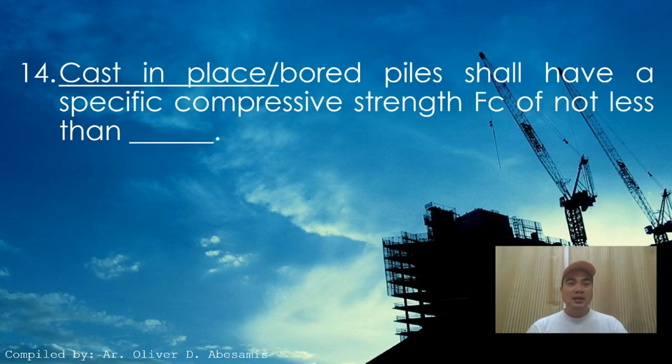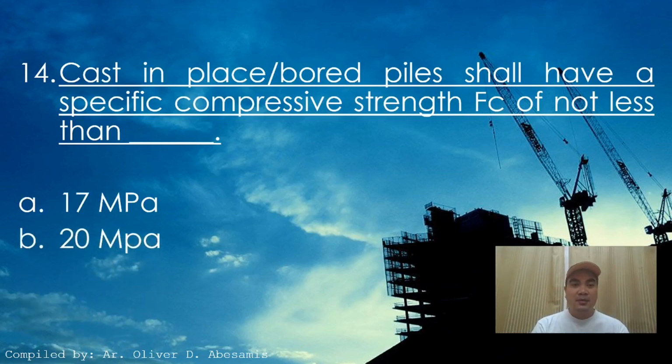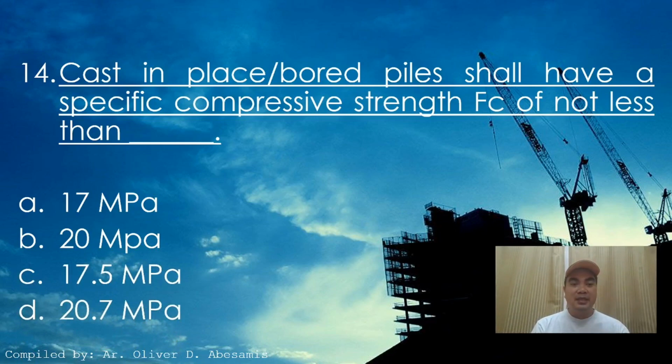14. Cast-in-place bored piles should have a specified compressive strength of not less than blank. A. 17 megapascal, B. 20 megapascal, C. 17.5 megapascal, D. 20.7 megapascal. Answer? C. 17.5 megapascal.